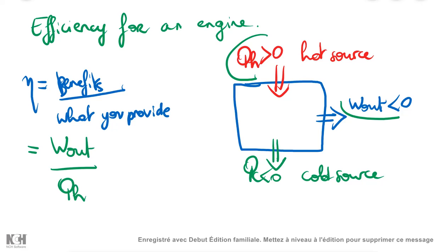But be careful here, it's important to add the fact that we are talking about absolute values. Why? Because when you consider your system and when you are making the thermodynamics calculations, you will consider the signs in the referential of the system. So here, for example, the work will be negative. But your eta, so the efficiency, is in your referential as external operator. So for you, it's something positive. So you need to add the absolute value so that you can have something that is not negative.